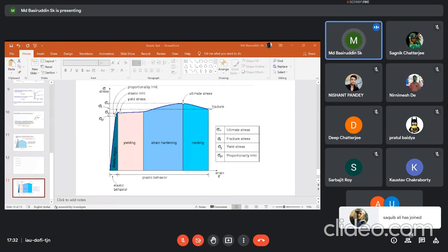But we are not talking about the machine's mechanical property, right? The machine may also deform, either elastically or plastically, depending on the load you are applying. So in order to get accurate values, you also need to think of your machine's mechanical property, because the machines are also made of either steel, or superalloy, or some ceramic material.